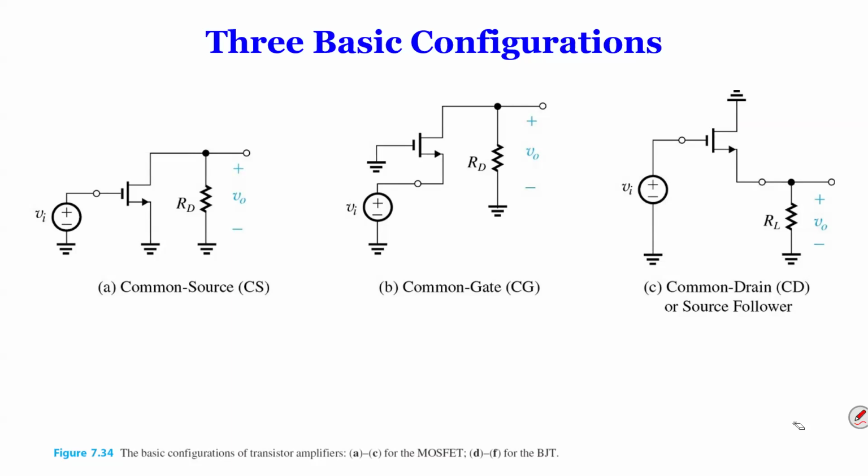So we assume that every transistor is in saturation mode, and we only included the AC parameters, no DC. For each of these, you can probably already think about it. This one, I can simply use a pi model, but this one, maybe not. What we can do is go through each of these and simply draw the models and see how they look. Again, as I said, it's not the end of the world. You can still do it.